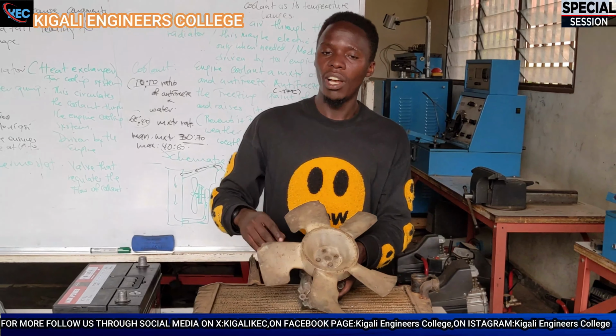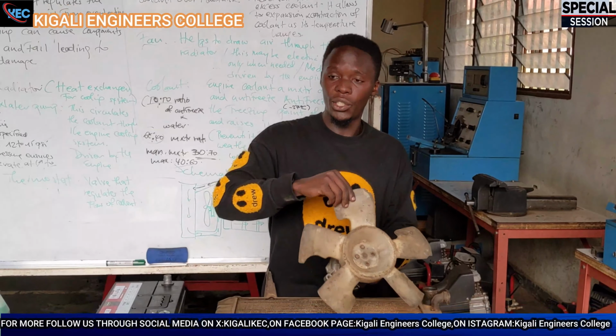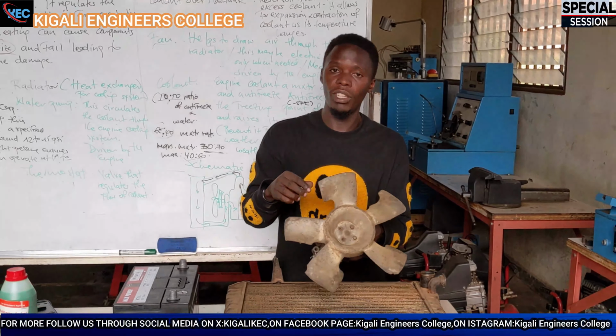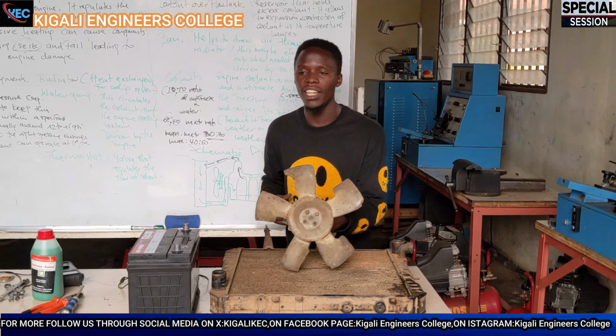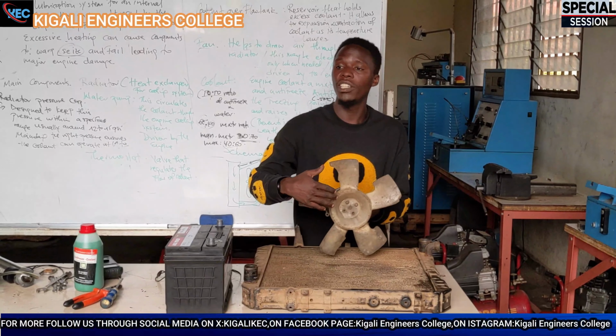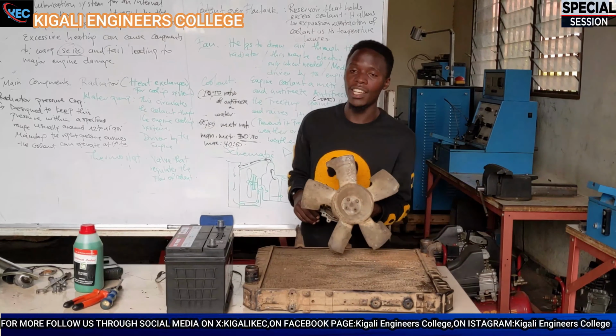It has to go in the clockwise direction. This is the fan, and that's the rotation of the fan. If it goes anti-clockwise, it will be pushing the air from the engine out to the atmosphere instead, causing the engine to overheat, as you can see.